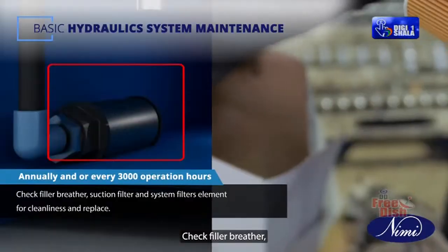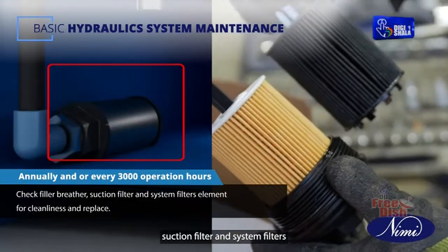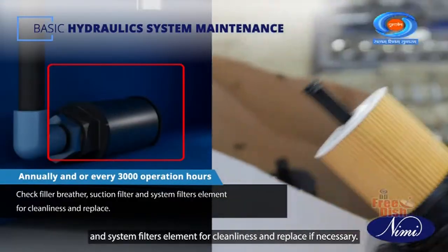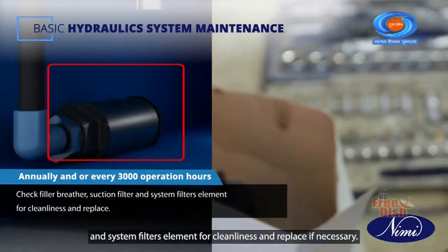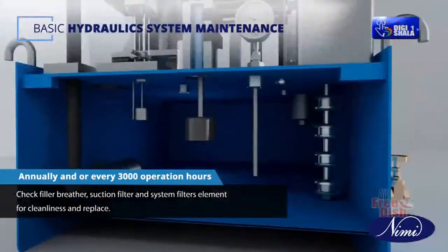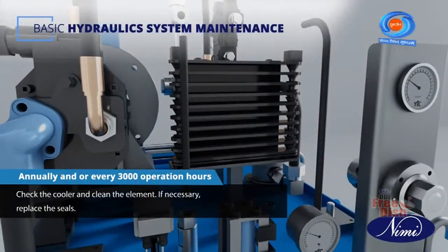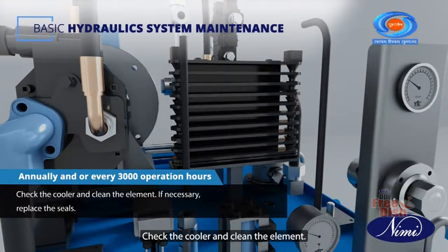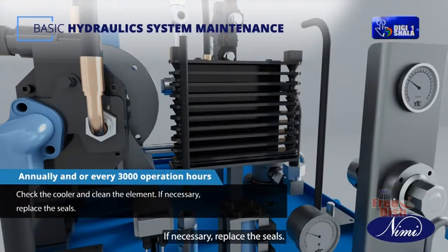Check filler breather, suction filter and system filter elements for cleanliness and replace if necessary. Check the cooler and clean the element. If necessary, replace the seals.